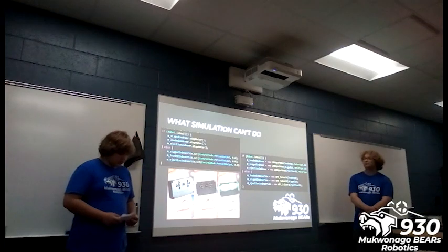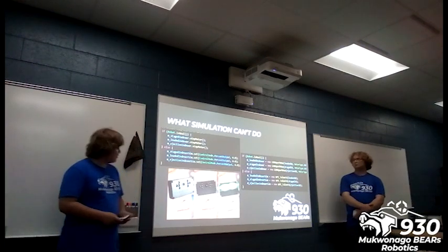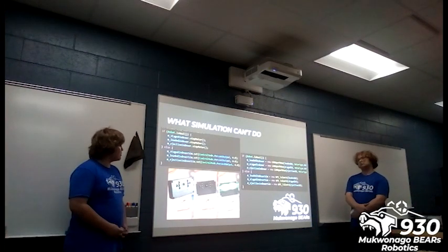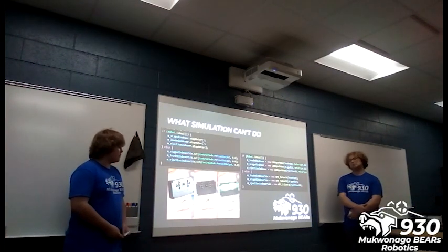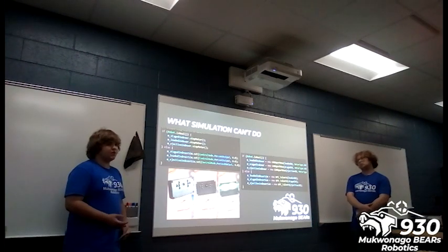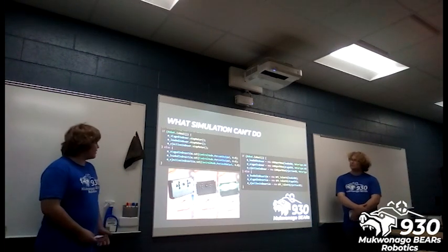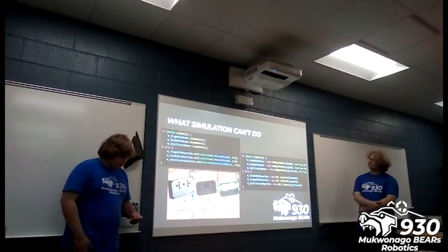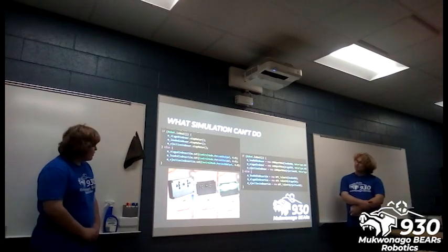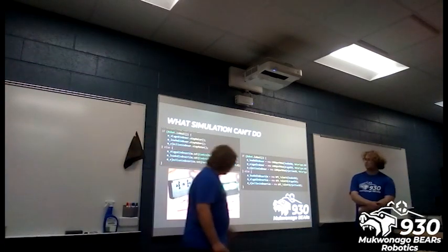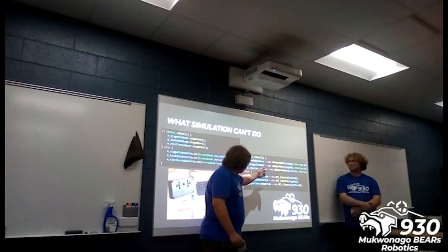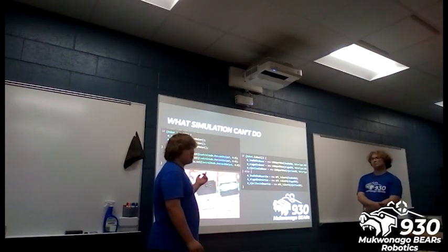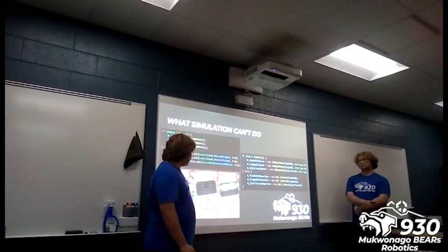But now we'll move on to some things that simulation can't do. First of all, you should always keep in mind that after using simulation, you should still test that feature with the actual robot, because there are a lot of points where simulation can be imperfect. One case of this is motors. You can see here we were using CAN Max and some other motors just aren't supported in simulation.